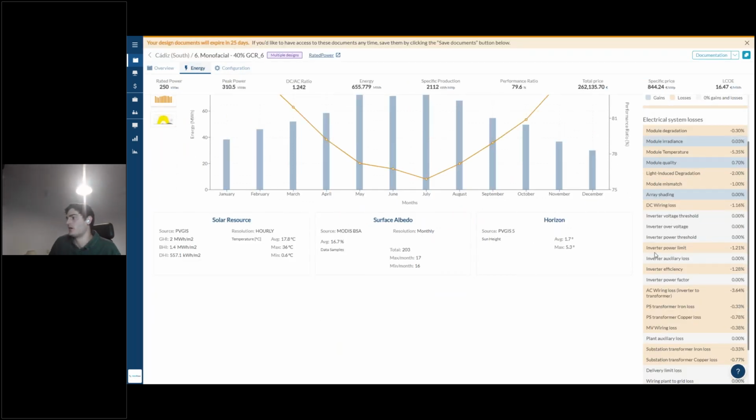And if we increase that DC ratio further, here is where we will find that these losses are too much when compared to the gain in the cost that we are reducing from the AC side. So we will prefer 1.18 because the energy plays an important role here, and we prefer that increase in energy rather than that saving in the cost of the inverter.